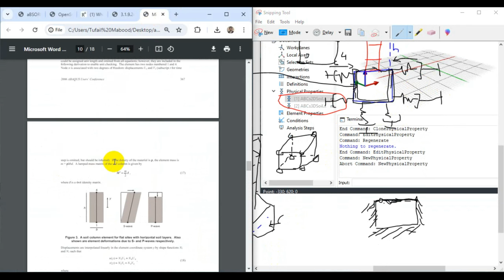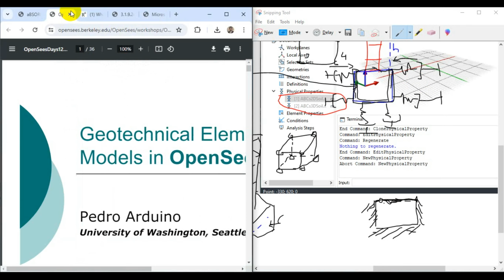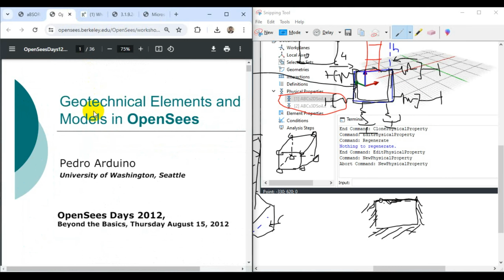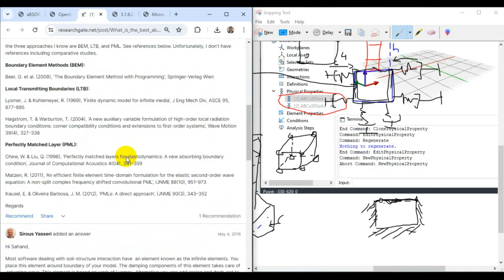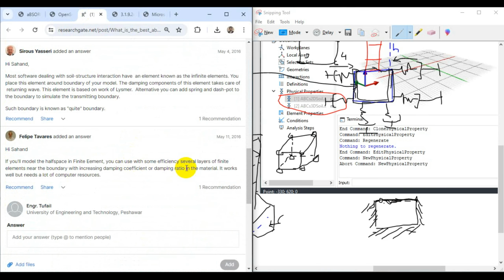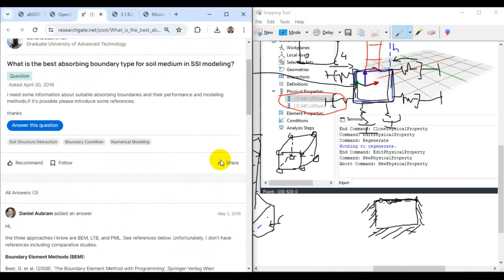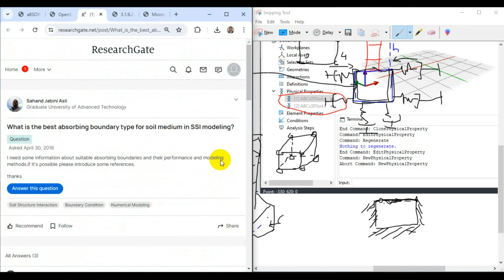So if you are using Abaqus, I think you can use the methodology of infinite element. And in order to define the infinite element, you need to edit the input file, because that is also not possible inside an Abaqus file.